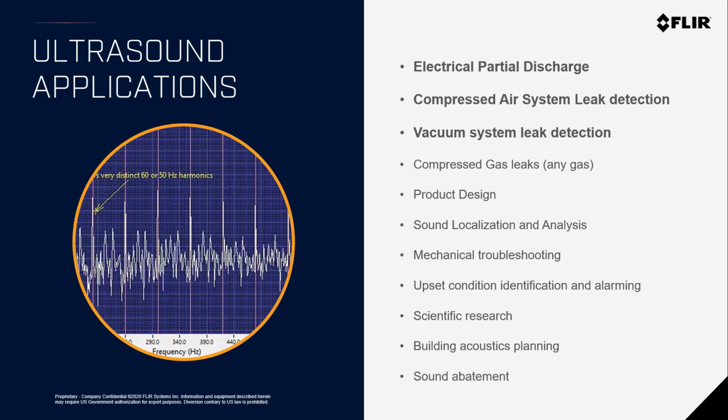So let's talk a little bit about the applications themselves, right? There are many applications for ultrasound technology. Electrical partial discharge, compressed air leaks, vacuum leaks, refrigerant gas leaks, and many more. But the ones that tend to have the biggest return on investment for most users are the three that we've highlighted at the top here. Electrical partial discharge, compressed air system leak detection, and vacuum leak detection.